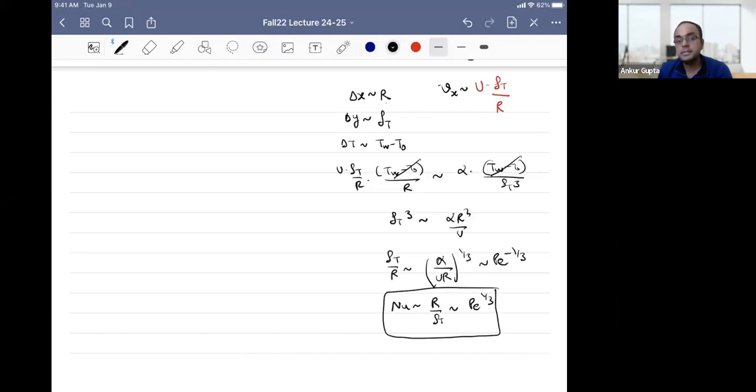And you may remember this is something you may have written in your undergrads, that the Nusselt number goes as Peclet to the 1/3. It might have been taught to you, but you can see there is a rigorous derivation behind it. You can actually also calculate it fully. The book has a full solution. And this is a very important result because flow around a heated sphere has been very important for chemical engineering. So Peclet number to the 1/3 you can calculate. And why 1/3 again? Remember, 1/3 comes because there is a no slip, and then there is a thermal boundary layer next to it.